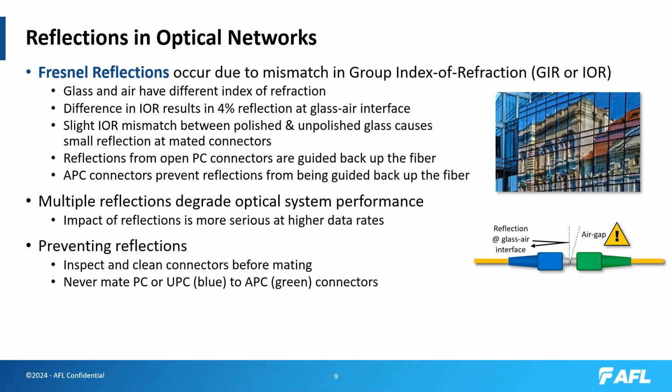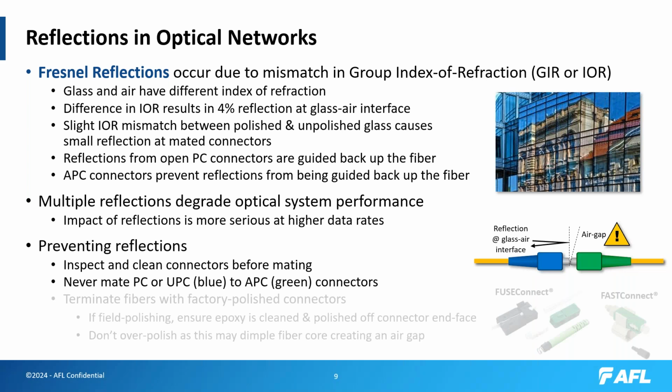And then lastly, never mate PC or UPC blue connectors to angle polished green connectors, because it will create that air gap. You will get an excess reflection off the perpendicular end face of the blue PC or UPC connector.